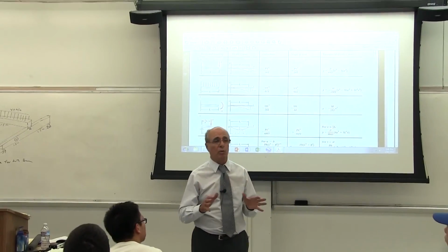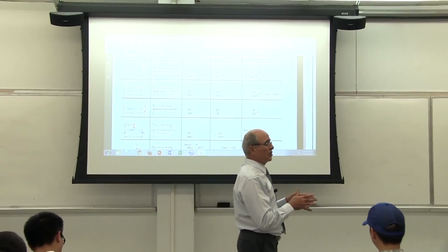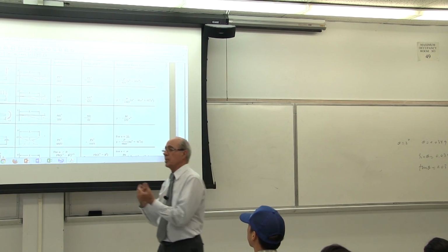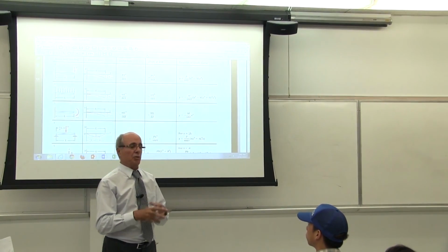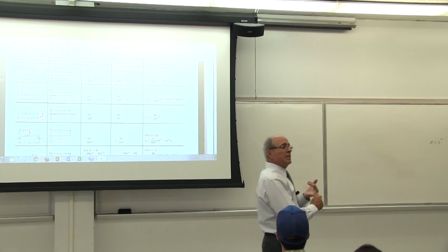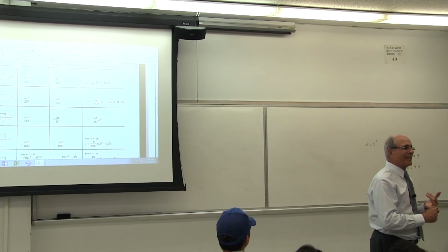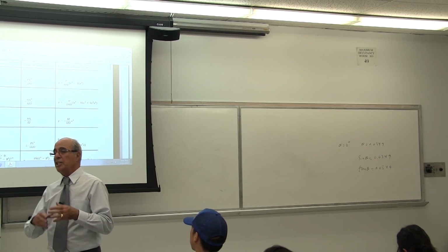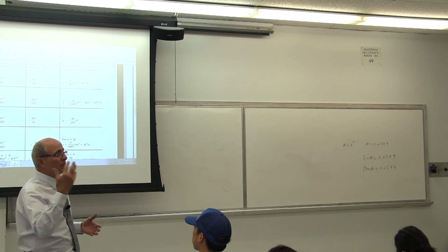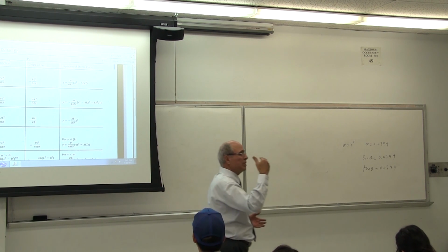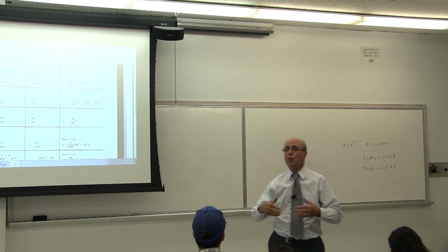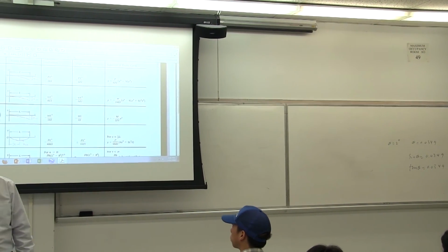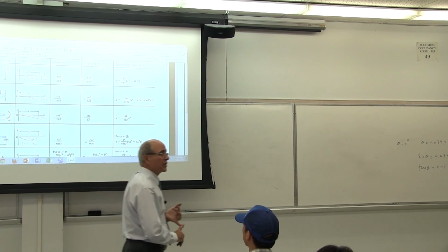Now, I need you to know this. In order to understand the next chapter, which I'm going to go quickly over, and there are lots of fancy problems coming at the end of it, which are the real life scenario problems, you need to know the strain, shear strain, which is what? Gamma. You need to know the normal strain, which is epsilon. Not in one dimension, in three dimensions. Epsilon equals sigma x over E minus nu sigma y, Poisson ratio, shear strain, normal strain, everything that you learned in chapter 1, everybody in ME 218, plus you need to know the Mohr circle,